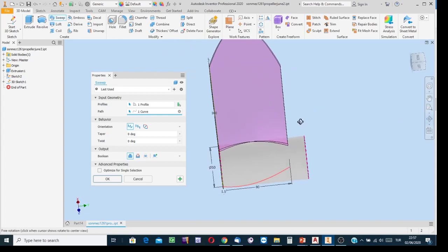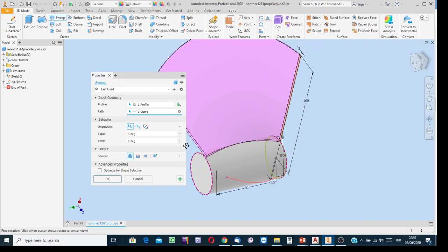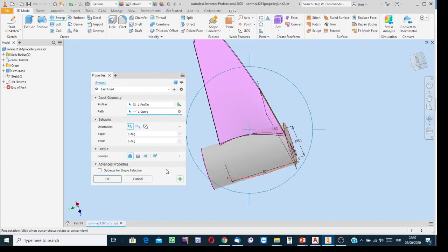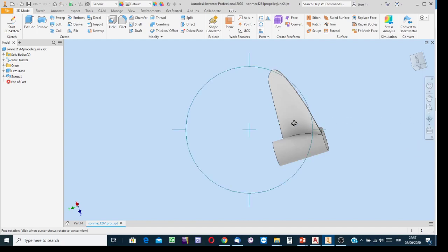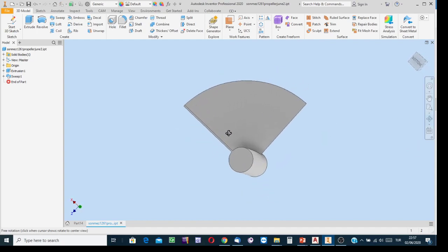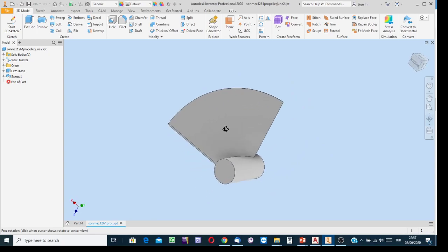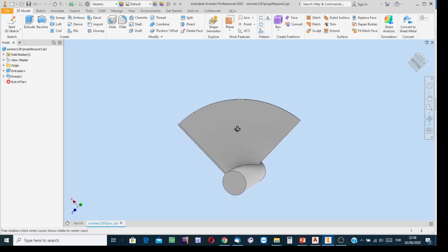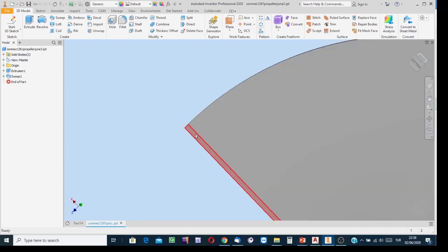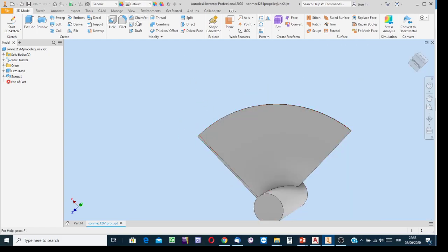From the simulation I see that it is okay. And then click on the OK button. That is it. Have a look. One of the blades of the propeller, its main part, is now available. Okay, and then round the edges. Of course, the rounding value is also determined by the designer to prevent some undesirable vorticities while the propeller is rotating.